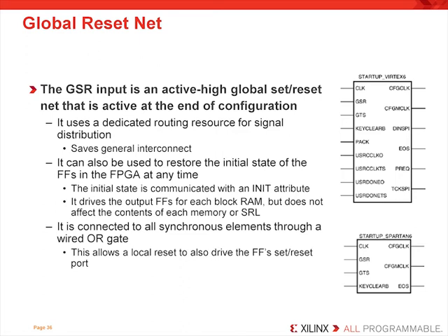It is useful to understand that each flip-flop has the ability to have an init value associated with it. This initialization value is set after configuration and after any time the GSR-net becomes asserted. The init is often inferred by your synthesis tool if you assign an initial value in your HDL, and we'll talk a bit more about this later on. But that is different from the GSR. The GSR is an active high global reset functionality that is coupled with a dedicated routing resource for the signal's distribution. The GSR can also be used to restore the initial state of the flip-flops at any time. This is done with the init attribute.